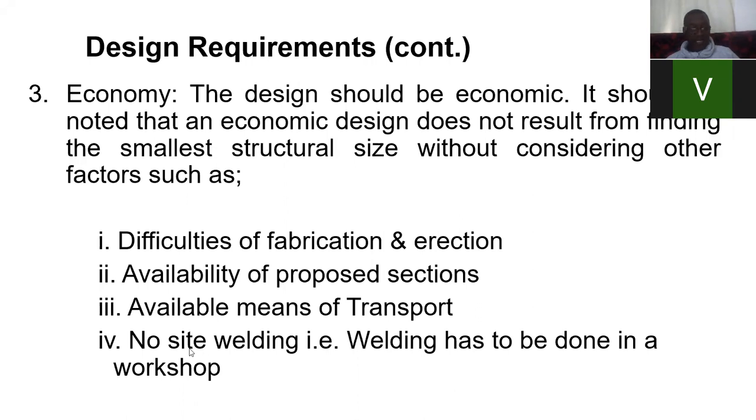And again, we also discourage site welding. Instead, all welding works has to be done in workshop. Influence of oxygen: too much oxygen in welding reduces strength of weld joint.